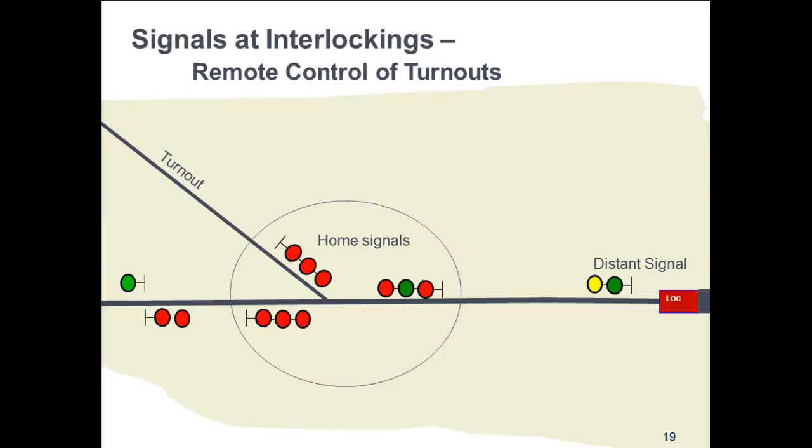Okay, this is why we don't clear signals until just before a train is due to arrive, because there is a time delay associated with making a correction. The dispatcher cancels a home signal and they revert to red, which means stop. A 5 to 8 minute timer is activated to accommodate safe passage through or stopping of existing trains already on the route.